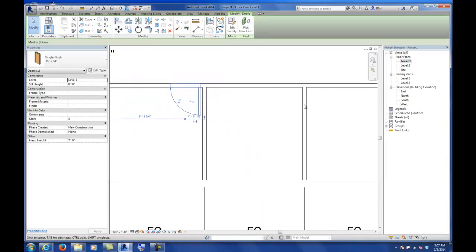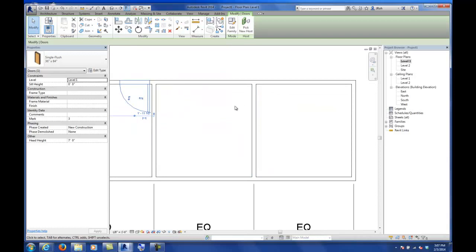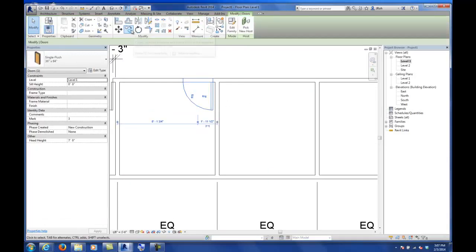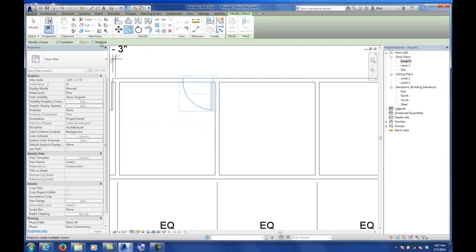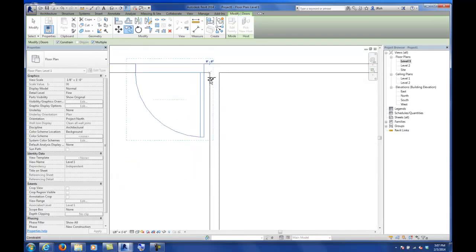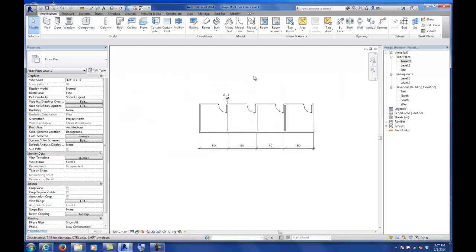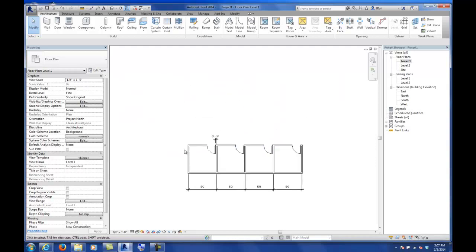over and over. Notice I can't copy over and over again. And that's because when I hit the copy command, notice in the options toolbar, there's this little checkbox where it says multiple. If I check that, that means I can go ahead and copy this over and over again as I move down here. So I've now got this office block and these walls and so on.